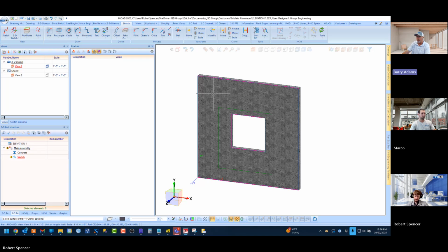Surface boundary. And then do I have to define that surface? Looks like I did, or just click on the surface. Just click once on the surface and then middle mouse button to apply. And it's telling you this down here if you get confused.